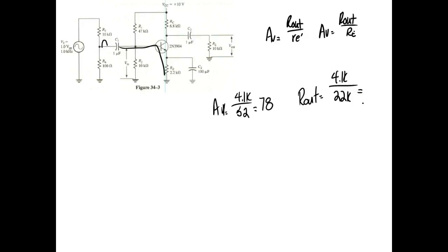You understand that? Now my input impedance goes up, right? You understand that? So we calculated our input impedance wrong over there. Let's redo our input impedance. It was my fault, because we were really, really off. I should have said something's got to be wrong. So this is 10K. This is 47K. It ought to make y'all feel good when I make mistakes, right?